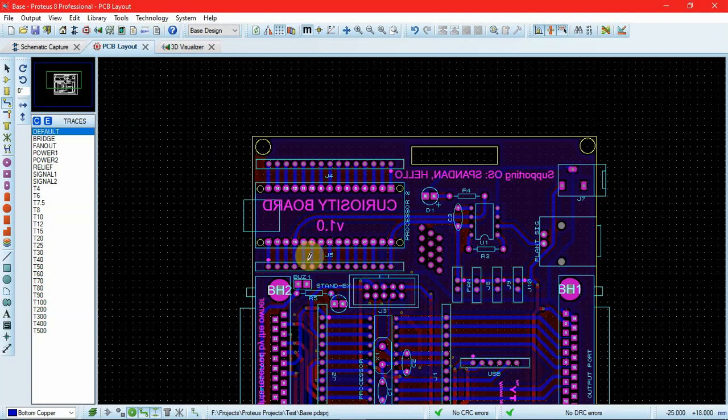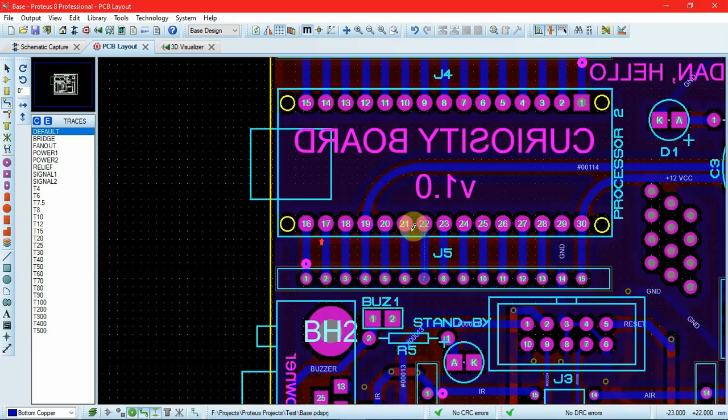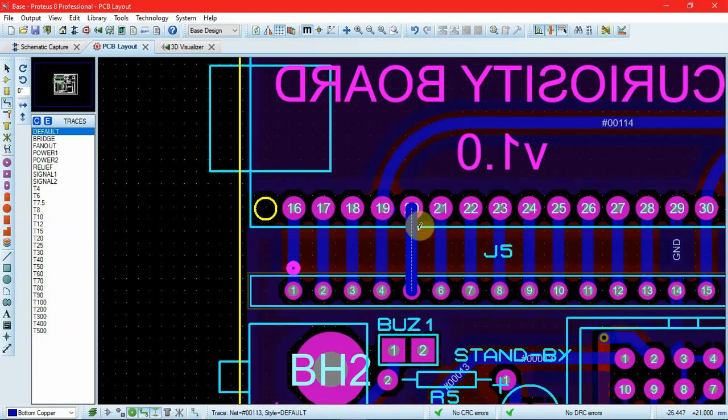There are various reasons to use the teardrop fillet in PCB. It may reduce mechanical and thermal stress where the trace joins the pad, resulting in less hairline cracks in traces. It helps to enlarge the PCB manufacturer tolerance of the drill to the pad. This makes the production of the board easier and reduces rejected boards during production. So I'll just demonstrate the difference between a normal connection and a teardrop fillet connection.